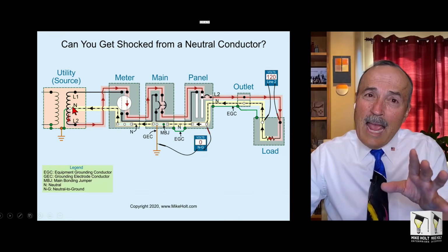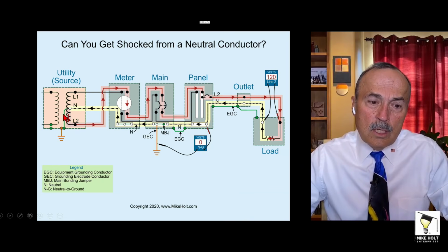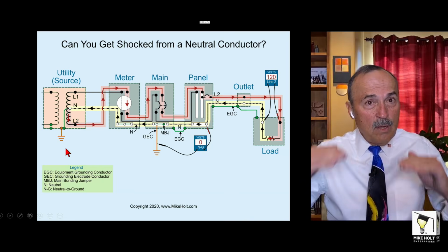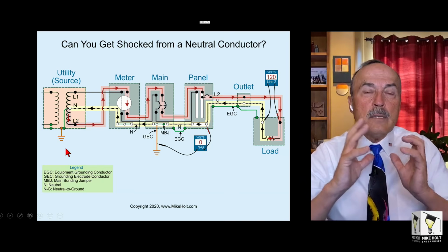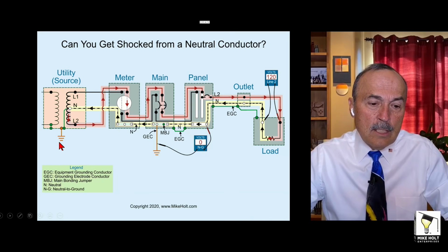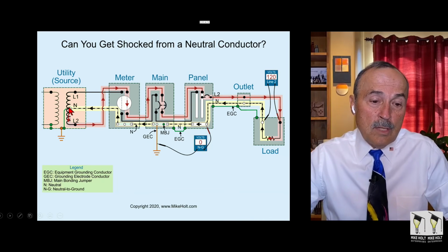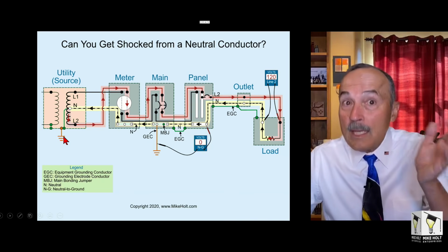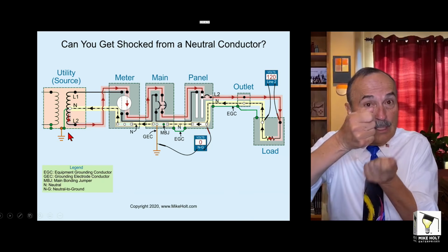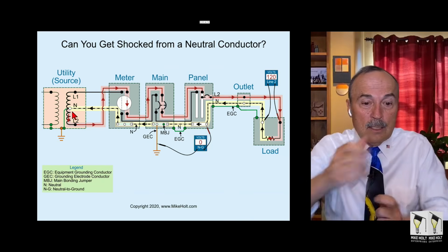Now this is a little technical. You see this neutral conductor right here? This neutral conductor is actually grounded. That means we've established what's called system grounding, that neutral point and this point in the earth. If you took a voltmeter, and you probably should do that, between that neutral point and the grounding point, how many volts are you going to measure? What do you think? 0, because it's measuring the same point, right? You get the wire at both ends.